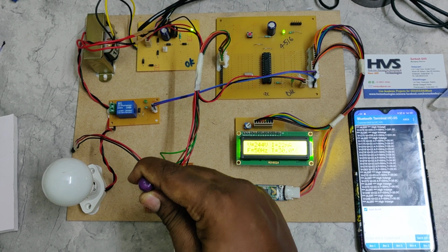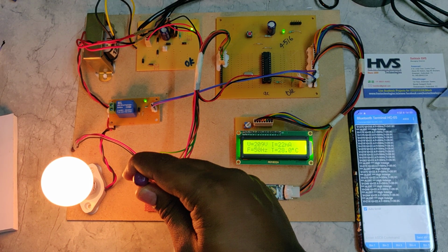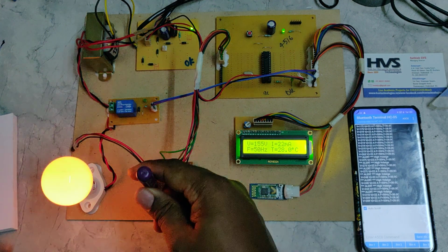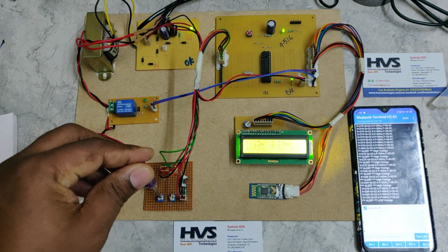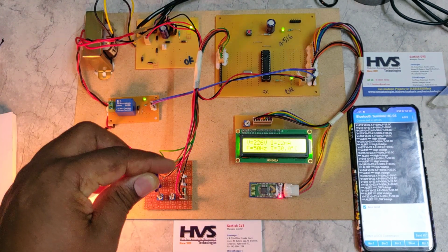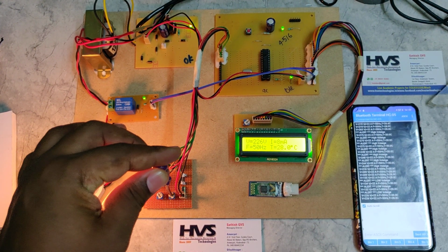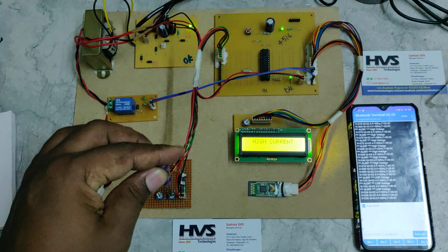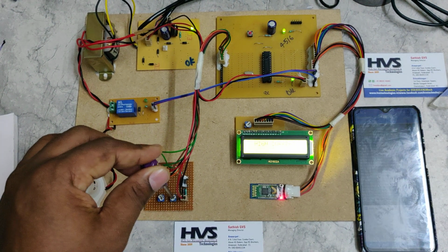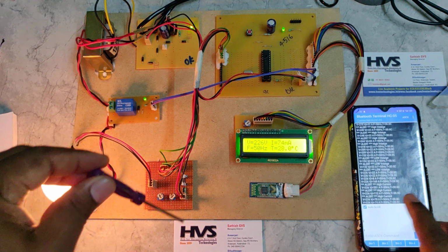When the voltage is set back to around 240, it's a normal voltage, and now the relay is switching back to connect to the load. Now I am decreasing the voltage, that is the low voltage, and making it normal again. Coming to the current, we set 100 amps for that, and when it is more than that, it will automatically be controlled, and we can observe the same alert message is sent to the Android mobile phone.